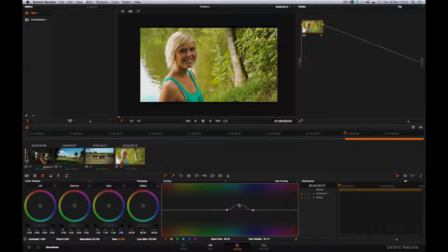By moving a third point in the middle of the selection, hue, that is the color of the delimited area, can be adjusted. The points can be erased with a right click. If I erase the limit points, no selection is activated, so I'll be changing the hue parameter for the entire image. This way, we'd also be able to adjust the color of the grass, for example. The other curves work similarly.